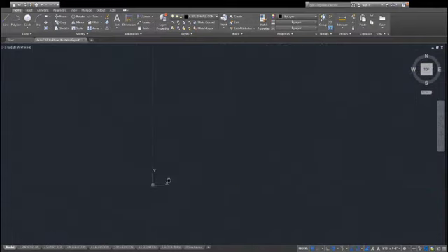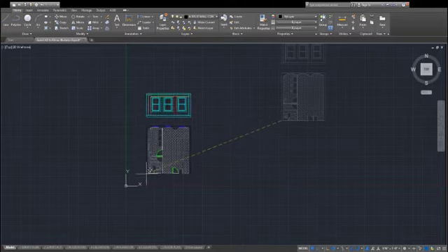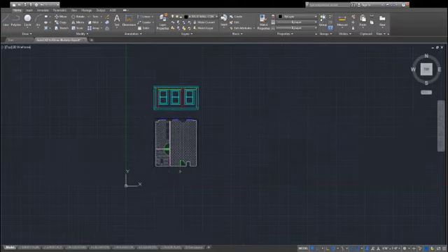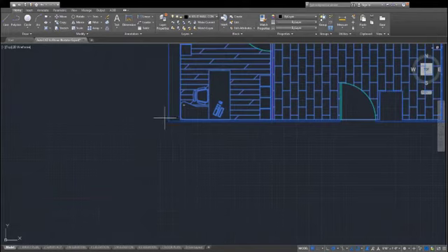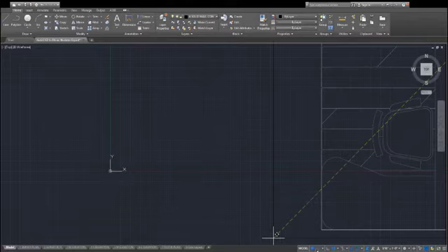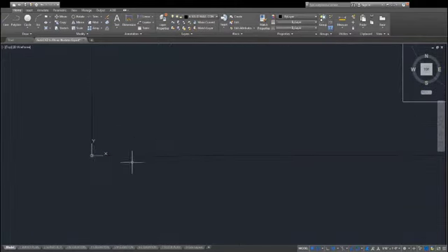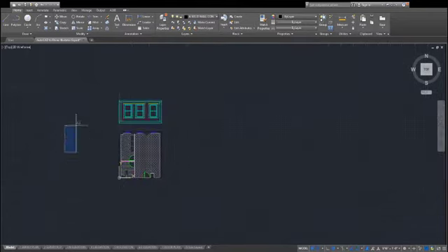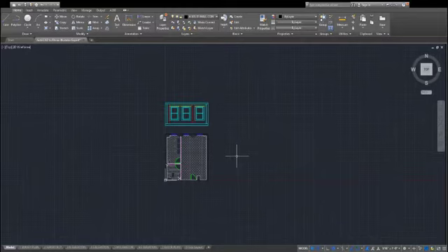So in this case, we have a very small portion of drawings, and it's quite easy to put that into the center. So we're going to use the move tool, and then we're going to lock that corner all the way up to the 0, 0. Now you can use the snap to grid to snap it perfectly into the XY coordinate if you like. And this is ready to go in terms of exporting to Illustrator and Rhino.